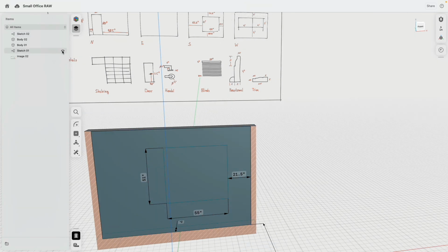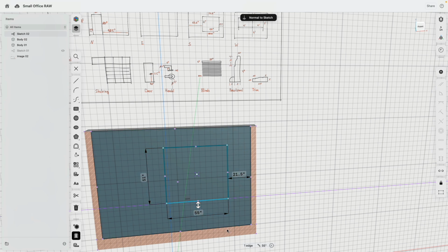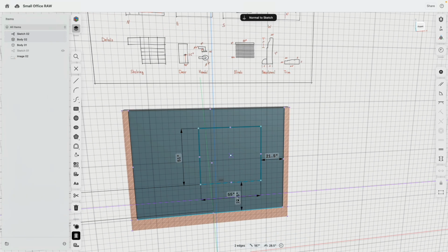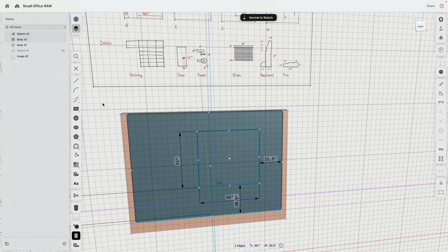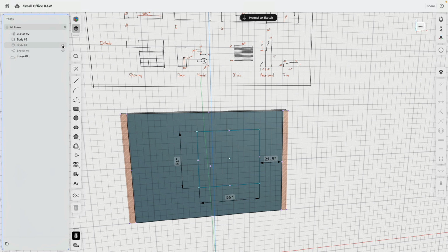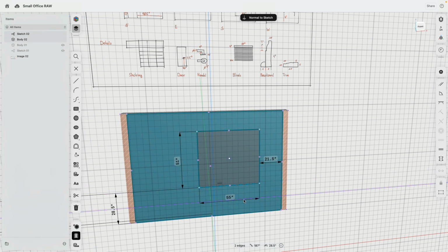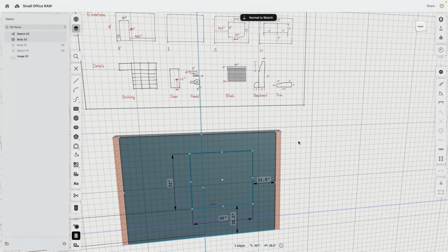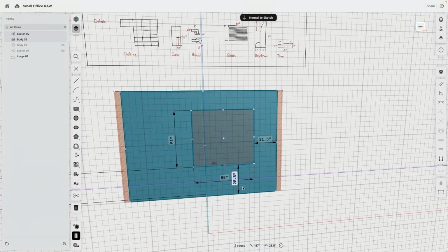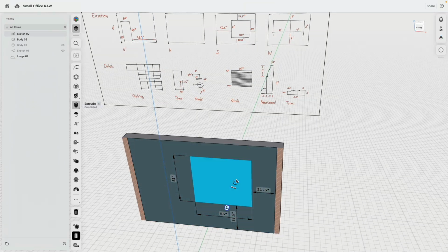This is selecting that sketch that I don't want. So I hide the sketch. So now I only can select the geometry. And here that distance, by the way, hold on, I'm going to hide the floor. So now I'm basically selecting the lower edge of the wall. And that is going to be 30.5. Very good. Now I want to make an opening for the window.